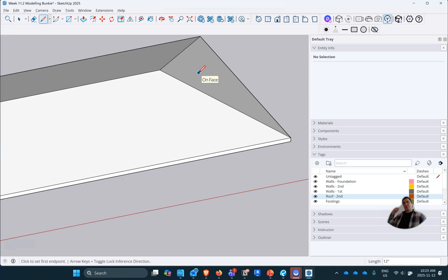And so here's a technique that we'll sometimes do if we have different roof slopes. When you're visually looking at the building, our edge is 5/12, and so if we keep our dormer roof 5/12, no one's actually going to know that our bottom part is a different slope because you're just not going to be able to see that in this direction. And so I'm going to find my here. So we're going to go up 5 inches here, and we're going to go back to there, and we're going to go up our vertex like this.